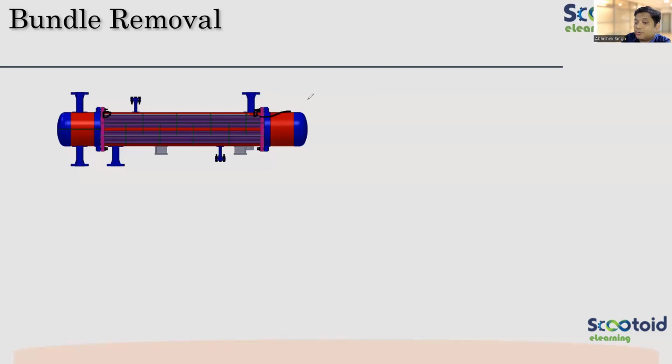So can I take this tube sheet out with the bundle? Whether this will allow? It's completely welded, guys, right? So it will not be possible to remove the tube bundle in this configuration. That is the reason we cannot access the shell side, right? I need clean fluid for BEM type of heat exchanger because I cannot clean the shell side. I cannot access.